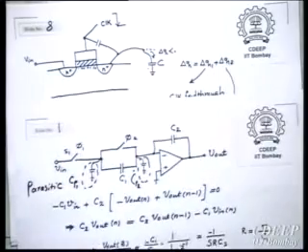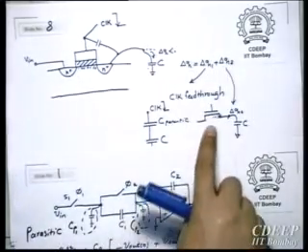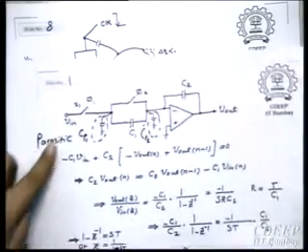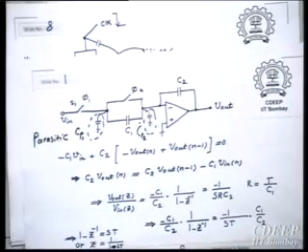And the amount of charge which comes from the channel depends on the value of Vin. It's not a constant value, because if it was a constant value, we could just use offset compensation. But it's not a constant value. Therefore, it changes with Vin, and therefore it creates nonlinearity.